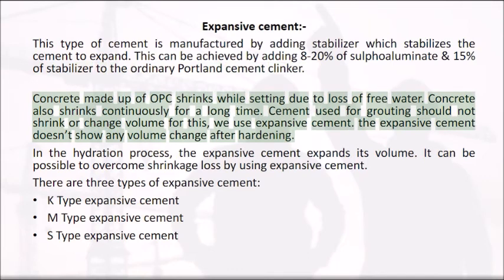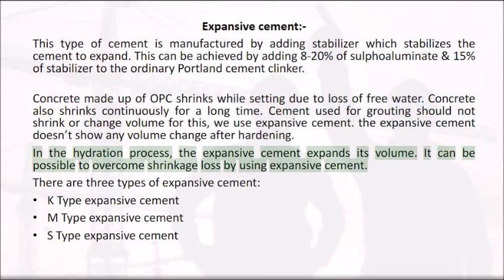Concrete made up of OPC shrinks while setting due to loss of free water. Concrete also shrinks continuously for a long time. Cement used for grouting should not shrink or change volume. For this, we use expansive cement. The expansive cement doesn't show any volume change after hardening. In the hydration process, the expansive cement expands its volume. It is possible to overcome shrinkage loss by using expansive cement.